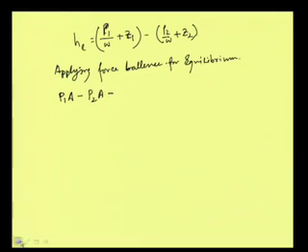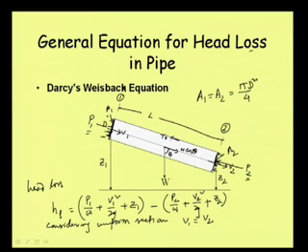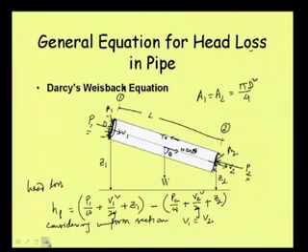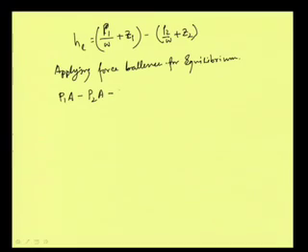Then what about the shear stress? The shear stress is tau 0. So, what is the total area? Pi d is the perimeter here, so pi d multiplied by the length will give us the surface area. As such, when we talk about the shear force or the shear resistance offered, we can write this as tau 0 into pi d L.